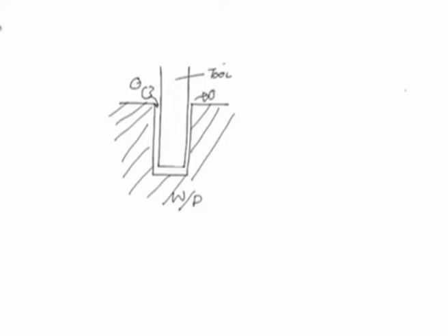Therefore, if the fresh abrasives cannot enter into this zone where the machining is taking place, the cutting performance will not be good. Not only should the abrasive reach this position, but it also needs to be flushed out from this position, so that a fresh cutting edge can enter.